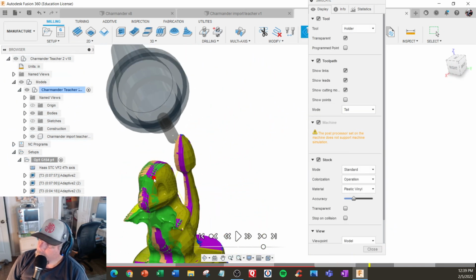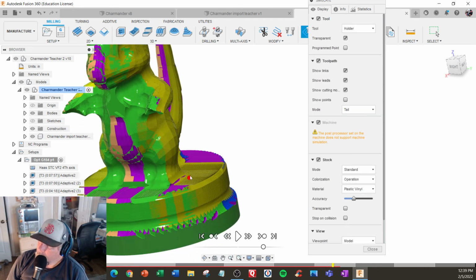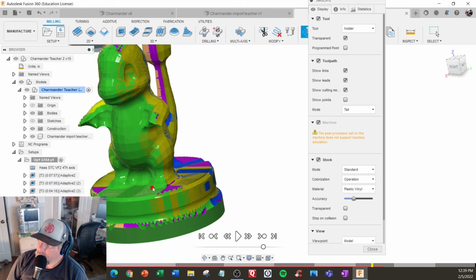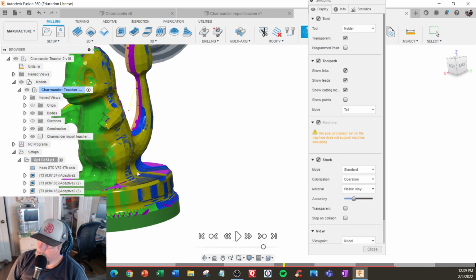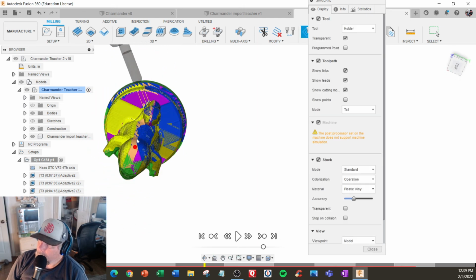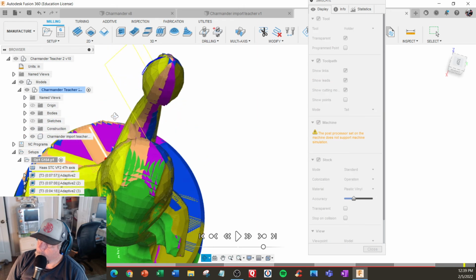So if you start to look at it from a multi-axis point of view, this surface here, we really couldn't cut that well. It's trying to attack it from all sides. It did get part of the round feature here. We couldn't get underneath. There's a gap underneath the tail. And we wanted to try to make sure we could get at this from different operations.